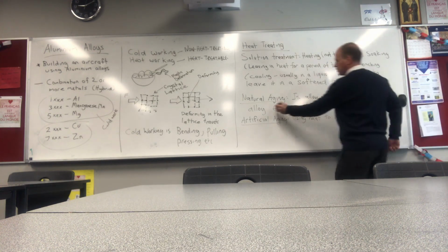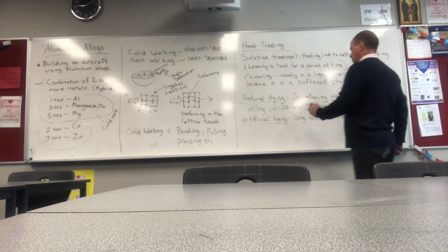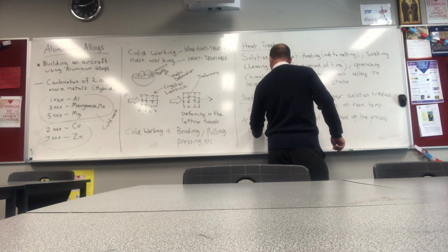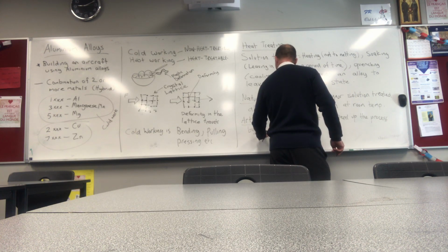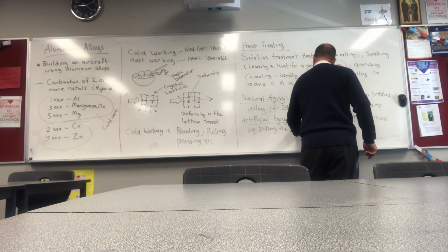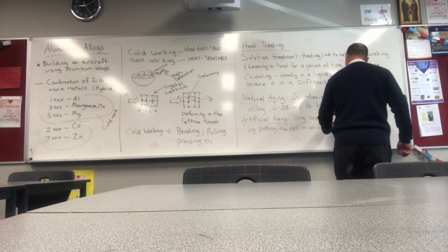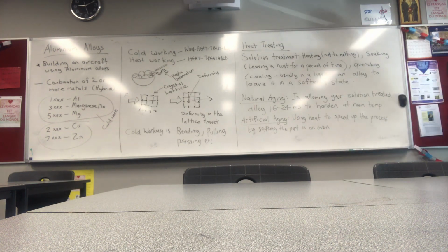It's 16 to 24 hours. And this is soaking in an oven. Use heat to speed up the process by soaking the part in an oven, and I think it's at 100 or 200 degrees, so it's not incredibly high amounts of heat.